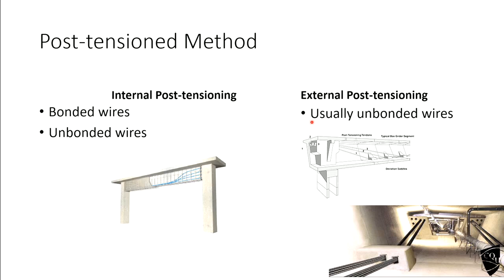You should be able to tell me that this depth should be enough for this load using a deflection check, and where you will provide the reinforcement, where you want to put the reinforcement bars, and how much, what is the value for Ast. Ast will be provided at a depth of small d, the effective depth. So you should be able to tell me to put this much of cover and others, so technically the small d you should be able to tell me.